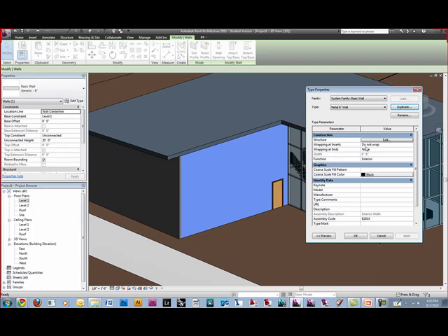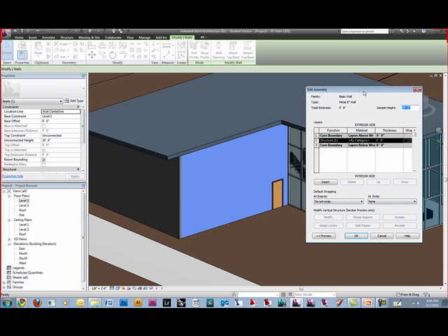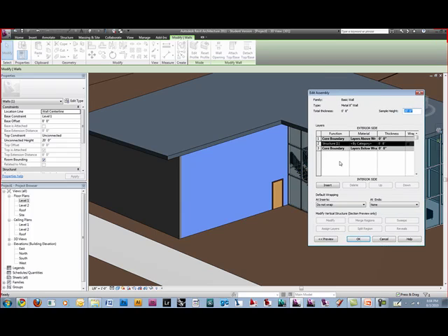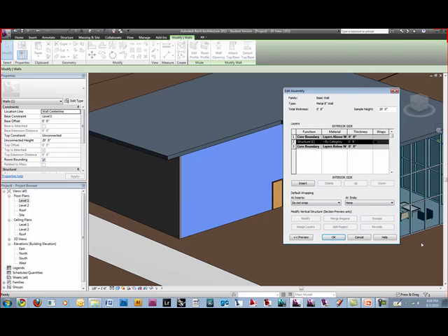What we want to do is hit the structure tab. We're going to edit the structure. This is actually a really neat thing. If you go into it right now, all you see is structure 1 by category. Really boring stuff. You probably don't really care that it's in there. The things you need to take note of are, at the top, it says exterior side, and on the bottom, the interior side. So depending on where your layers are depends on what's happening.